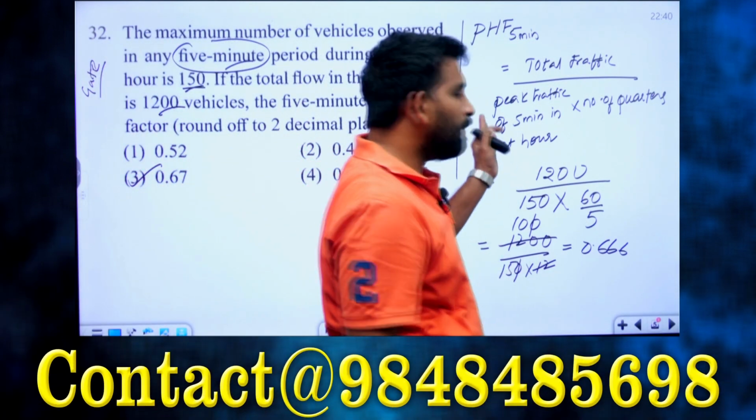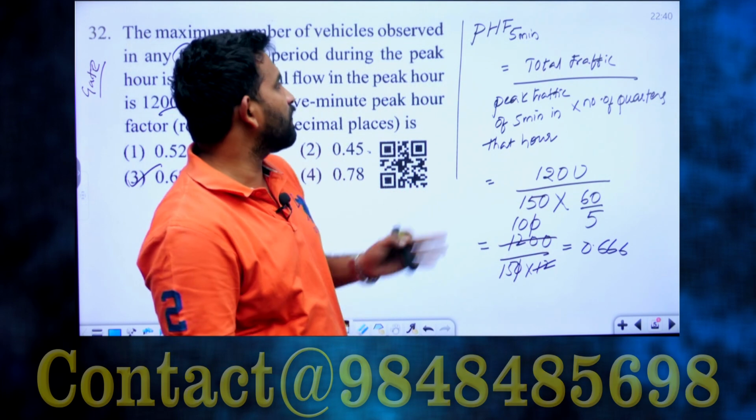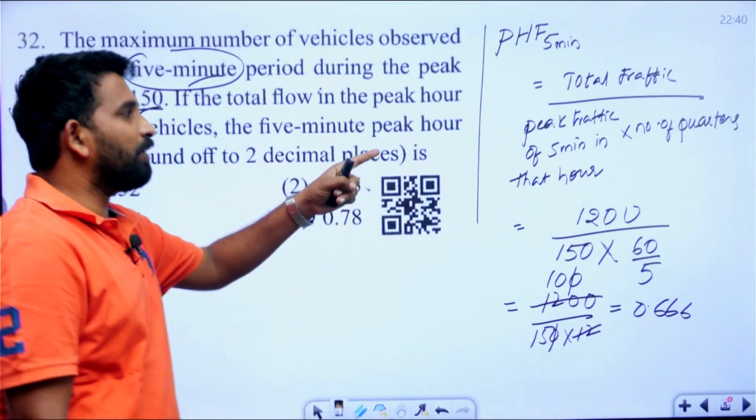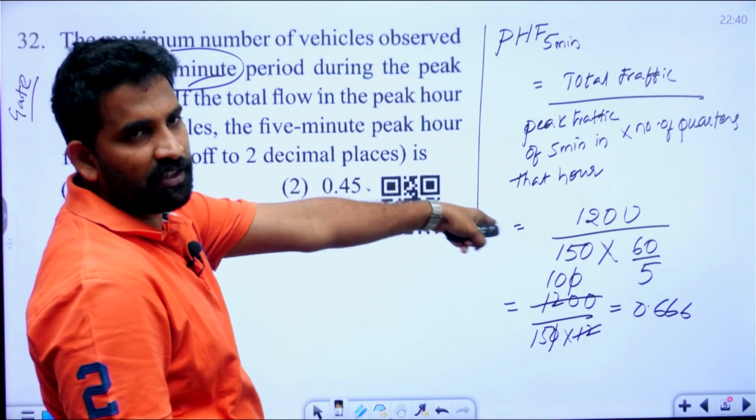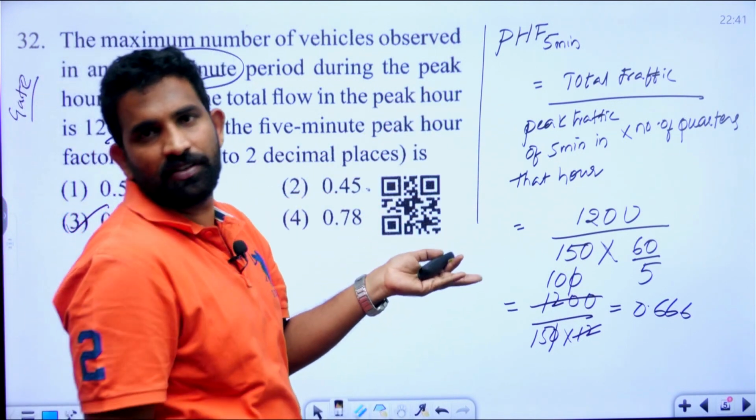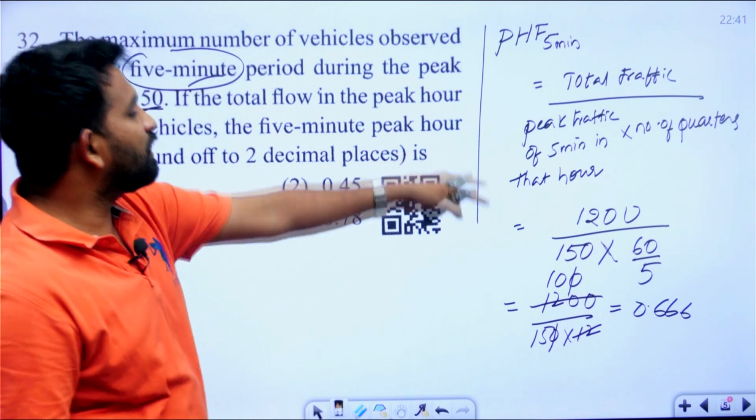So it is a very simple question. He is asking regarding the PHF, that is the peak hour factor of 5-minute duration. We just have to remember that formula so that we will be able to answer this question easily. Generally this PHF is used for signal designs. So this is a very easy way to solve.